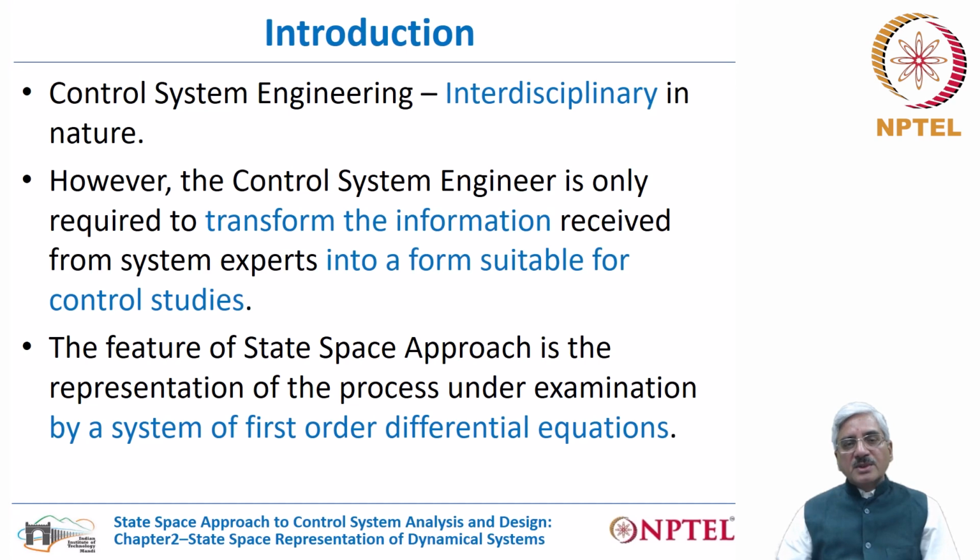As I have told in the previous part, it could be in the form of a transfer function if one wants to study systems based on the classical approach. However, we are not going to do that. We will very rarely make use of transfer functions. Most of the time, we will make use of the state space approach. And the feature of the state space approach is that in this, the system or the process under examination is represented by a system of first order differential equations.